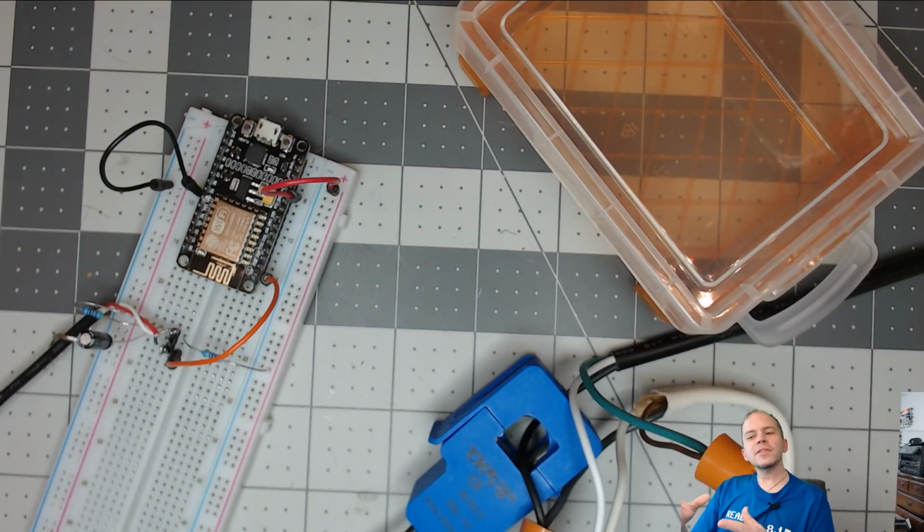If you're putting stuff in the panel, absolutely be careful. You can kill yourself putting stuff in the panel if you don't know what you're doing. Because typically the only way to kill the power in the panel, unless you've got some sort of outside disconnect, is to pull the meter off the side of the house. So, yeah, I am using that board from that link. And it does have that ATM chip we talked about.